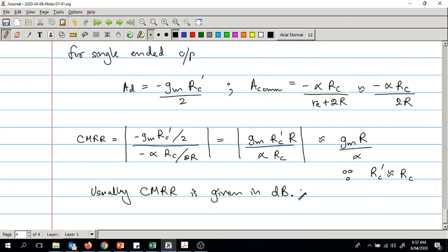When we look at the construction of op amp, we saw that it is actually the combination of differential stage at the very beginning, then a stage to combine the differential output into a single ended output, and then another gain stage.